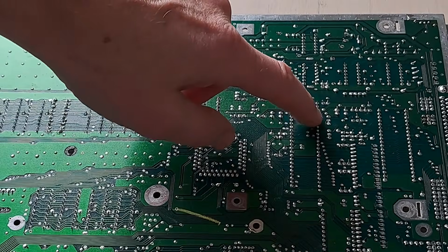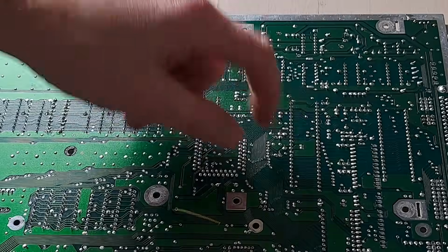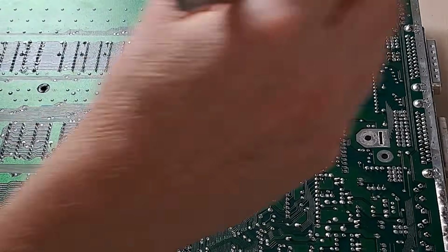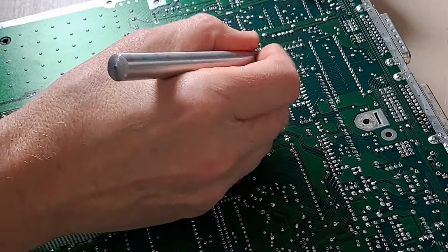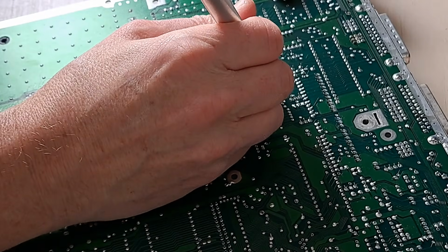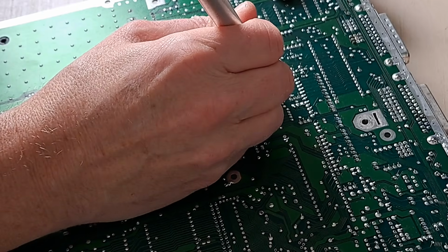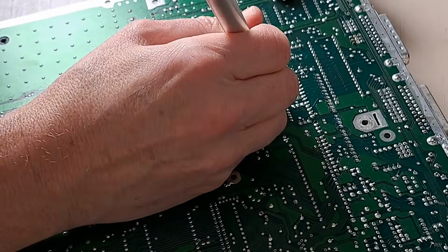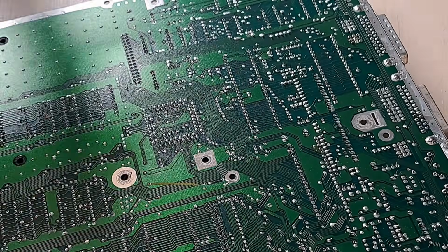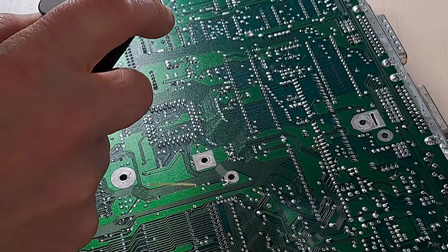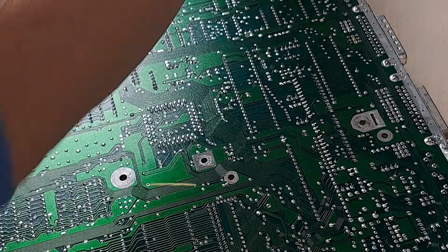And there's also that connection between the pins 2 and 3, which we need to remove. I'm trying to scratch that off very carefully with a knife. I have to be careful because the connection to pin 10 is right next to it, and we want to leave that intact. Although I'm aiming at a non-destructive modification, I do have to remove something here. But yeah, that can be easily repaired later with a jumper.